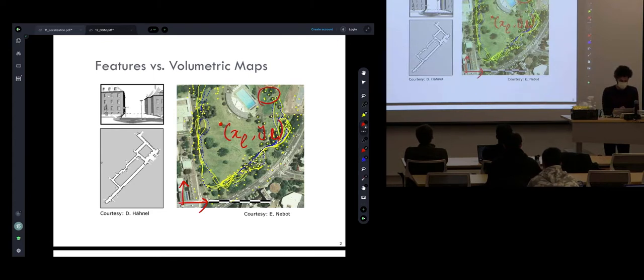Now, another idea that we work with today is representing the environment in a way that you could call dense. That means for every part of the environment, I am modeling some probability, here, a probability that a particular grid or point is occupied or not. That's another way. Maybe it's 3D. Maybe we want to reconstruct and show the objects the way they are. That's also a representation. But you can imagine that this 3D is, of course, much more computationally intensive than something like a 2D map.